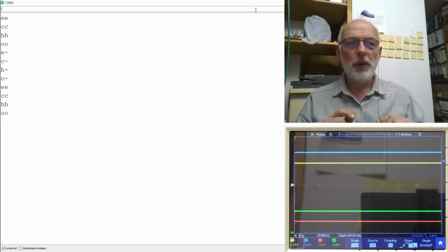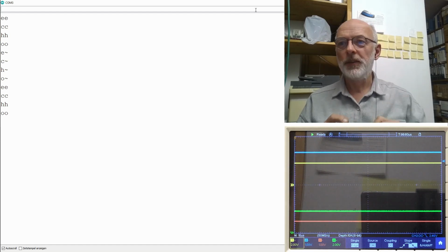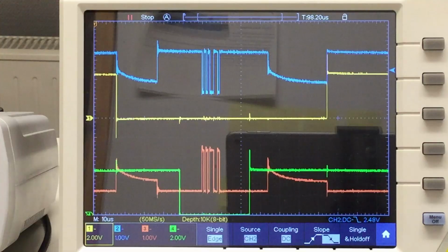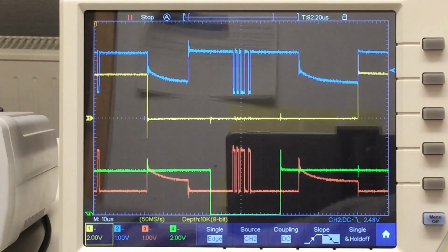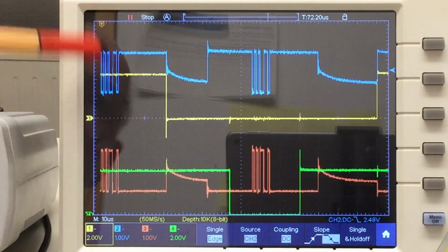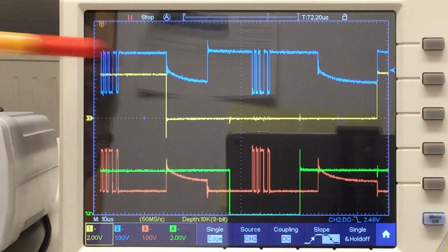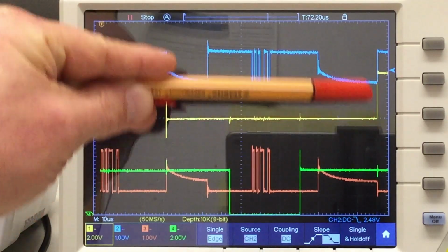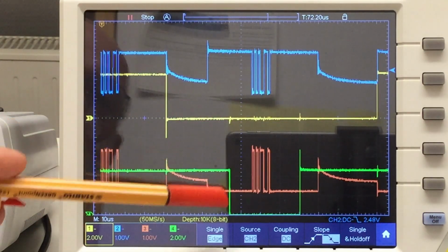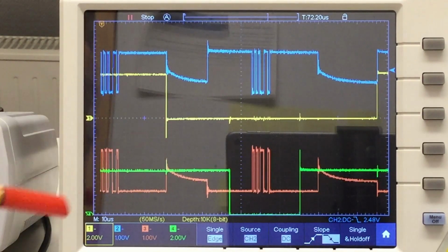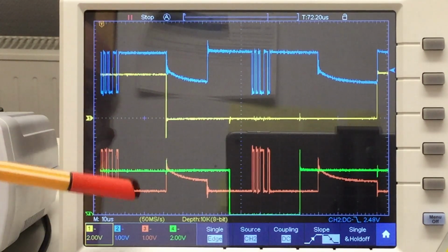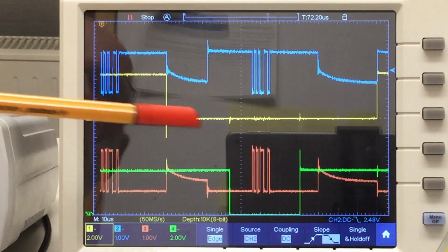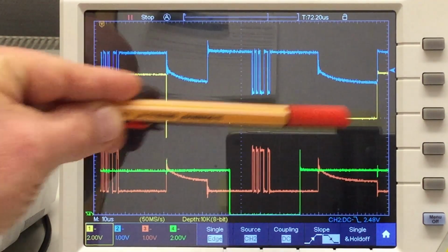Let's have a look at a normal transmission on the scope now. And I had to switch off some lights because of the reflections on the scope. There it is. Let's first scroll over to the start. Here's the byte the master is transmitting on the differential line over to the slave. And I also probed the master's transmitter enable line and the master's receiver disable line. So around here, our slave stops listening, and then our master is disabling its transceiver.